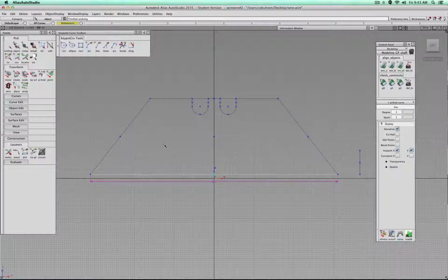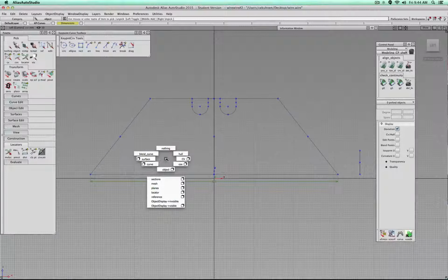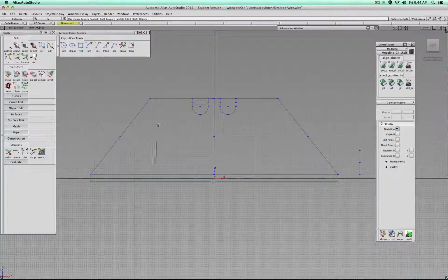Also, you might have seen that. You see, middle mouse button, Shift Control, move, rotate, Control Shift, left mouse button, nothing, object. The marking menu is gesture based. So I select the CV, I select nothing, I select object, I select surface.